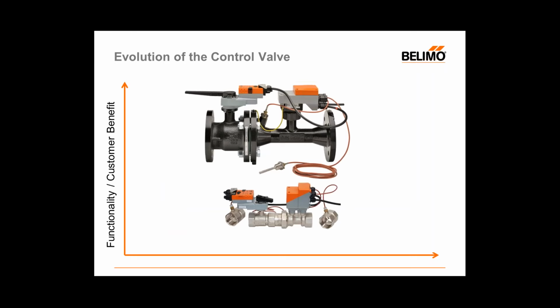With the Belimo energy valve, you have the option to also utilize power control where we're not going to modulate to a specific flow value, but you can modulate to a percentage of the maximum power output of that coil. So if you have a 5-ton coil, you tell the valve that it's on a 5-ton coil and it modulates from 0 to 5 tons by percentage. And this allows us to be pressure independent and essentially temperature independent as well.